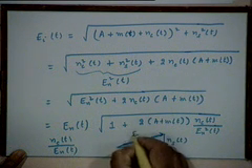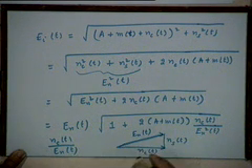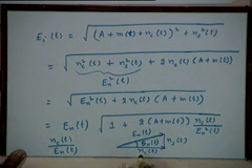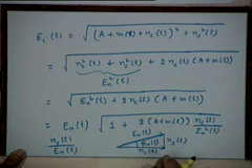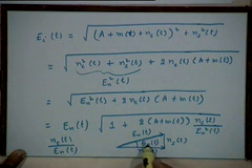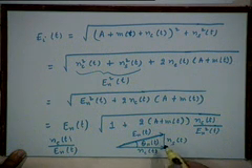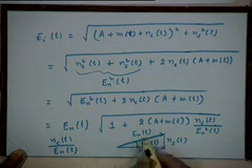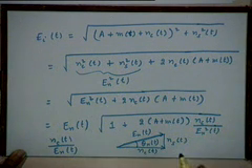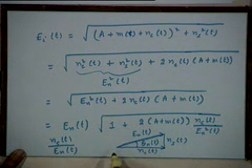Then this will represent your E_n(t), and this will represent your theta_n(t), where theta_n(t) is the instantaneous phase of the noise part, right. So, can I express this ratio in terms of theta_n(t)? It is cosine theta_n(t), alright.